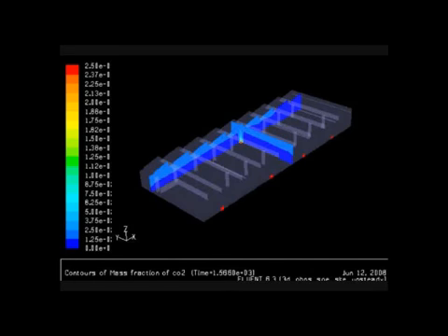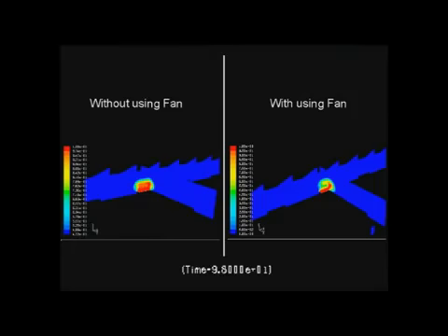The dense smoke is coming down slowly, and it came down to about human height in about, in this case, 15 minutes. The first ventilation system that we tried, obviously it was not good. Then we tried another system with roof extract fans, smoke-rated roof extract fans, and this was able to keep the smoke layer above human height for up to 1 hour, which was what the standard specified. We have to keep the smoke height above human height for up to 1 hour from the initiation of the fire. So that is similar.